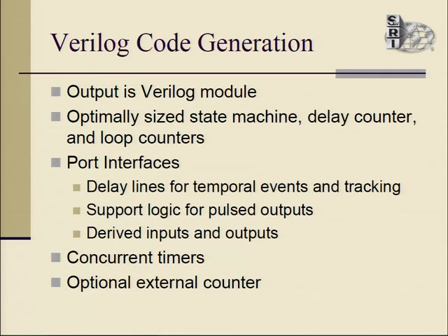But it will handle delay lines for all the temporal events, for tracking. It will handle all the logic for generating output pulses, as well as derived inputs and outputs. It also implements concurrent timers with the timer keyword we saw. For Verilog, we also have the option of providing an external counter. Because with very, very large counters, you can get problems with the size of the carry logic. You might want to have a more optimized external counter. That's supported in Verilog.